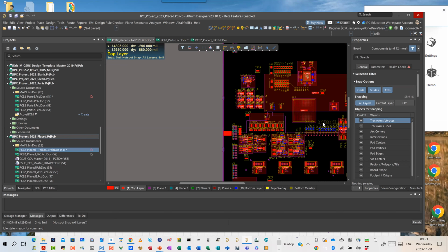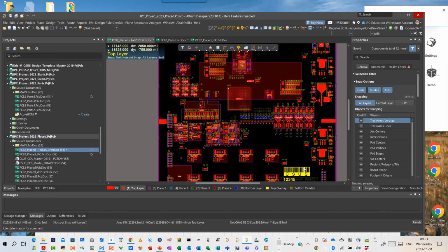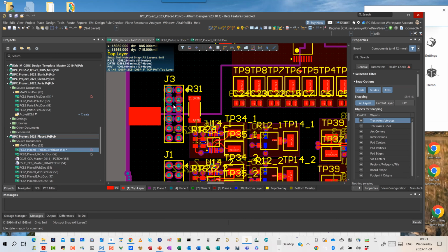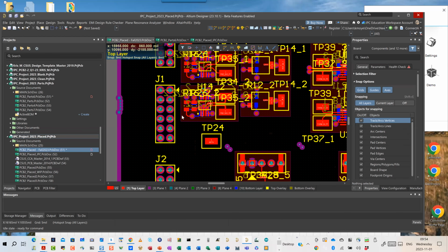But anyways, at this point, we'll go over this more next week, but this is the point where once you've created that split boundary, this is where you're going to use your rooms and start placing your individual circuits approximately where you think they should go in the board. I personally, since inputs are on the left, put my input connectors here. So this one's just a voltage monitor. That's the one we just looked at. Digital voltages are on the digital side. Analog voltages are on the analog side. Now this is just a voltage monitoring output connector here. Then I have the pressure transducer connector, the thermistor connector, and so on. Or I think I have pressure and thermistor in the same one on this one.